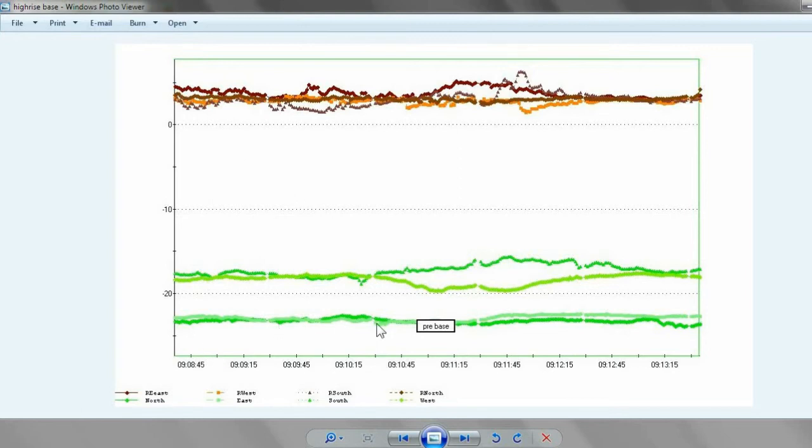So what we can take from this is that if we want to measure the pressures in the building, we need to run our tubing out at that level. Pressures are going to be highest at the very bottom. If we want to measure that stack effect pressure, we have to run our tube out at the bottom.